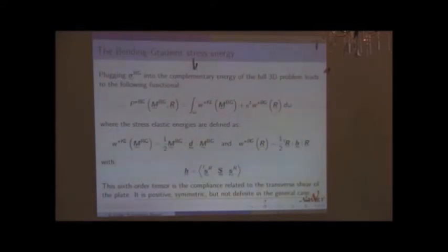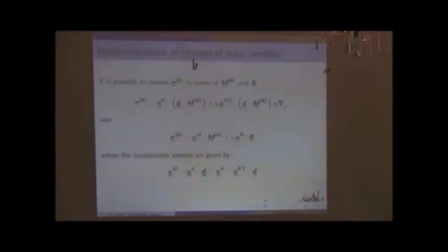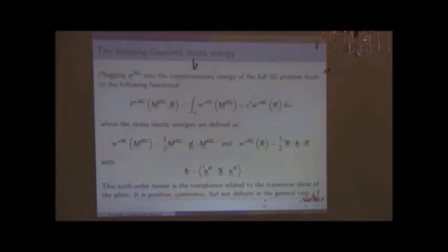This is the complementary energy, and I inject this approximation of the stress. I split the integration on the whole body into integration through the thickness and integration on the plate midplane.